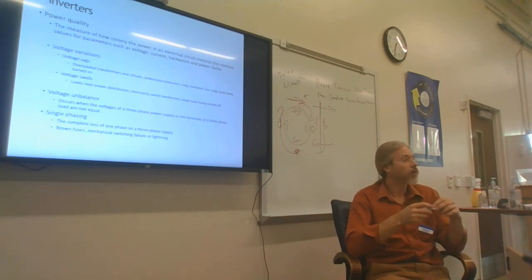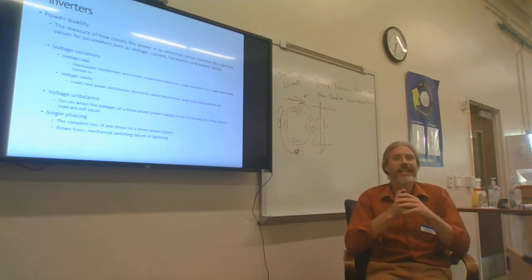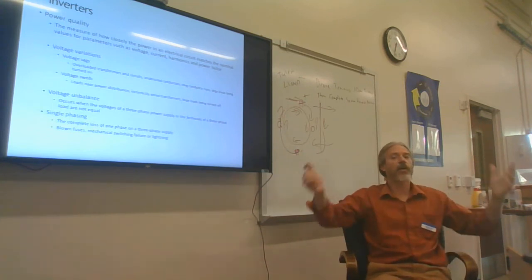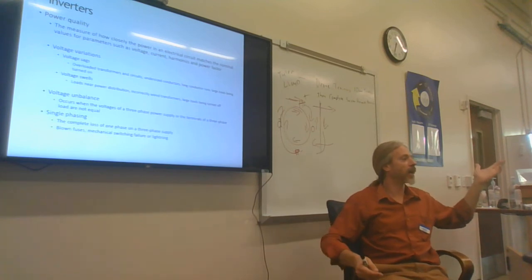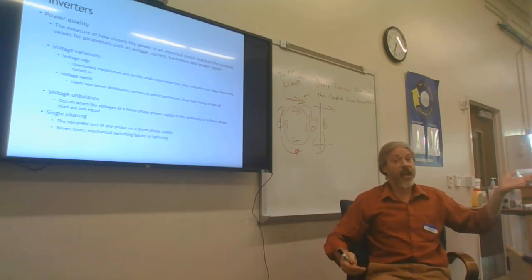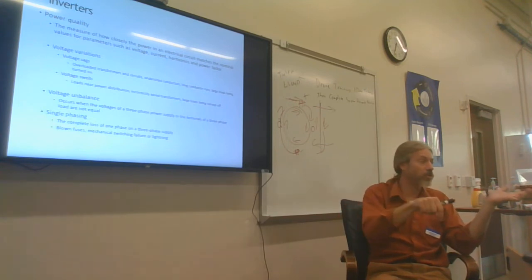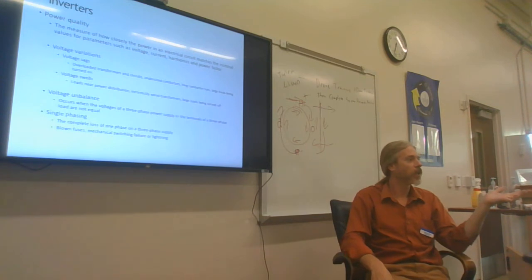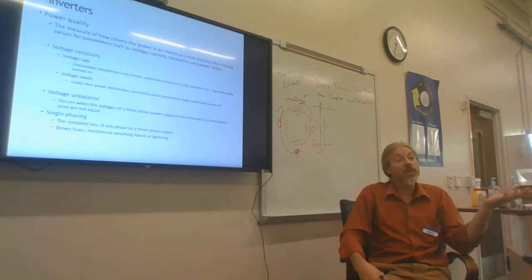What causes a voltage sag? Large loads being turned on simultaneously. Like when we had a power outage and Lazy Boy was coming back online. Every time they kicked on a big piece of equipment, we could actually watch the voltage drop in our system over here at Crowder. So when do we see large loads get turned on?